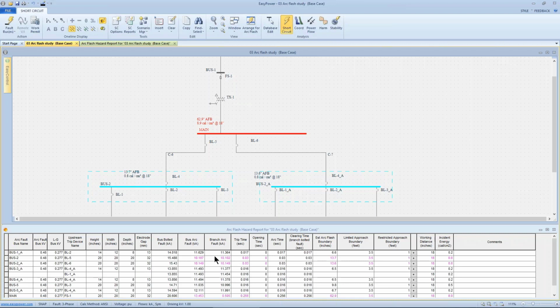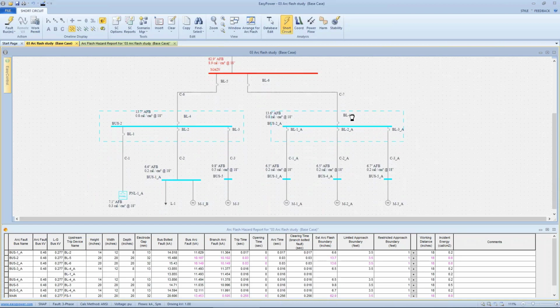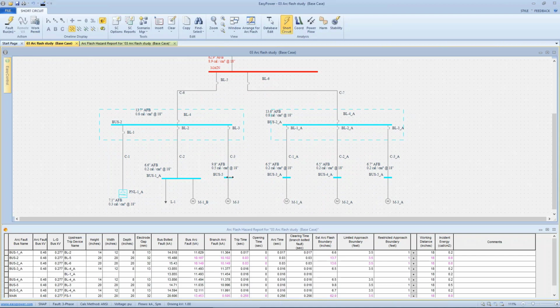And again, this is an automatic feature. It's not something we have control over. It's just an indication that that reduced current is being used. Where it's a dark type, the tool is using 100% arcing current because that's producing the most conservative result. And again, this is applied across the whole 15,000 volt range. So the heavy lifting as far as the calculations is being done by the tool. All we have to do is set it up correctly and we're off and running.